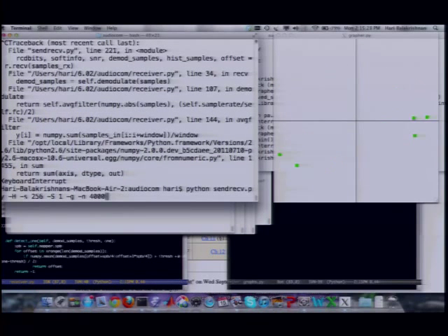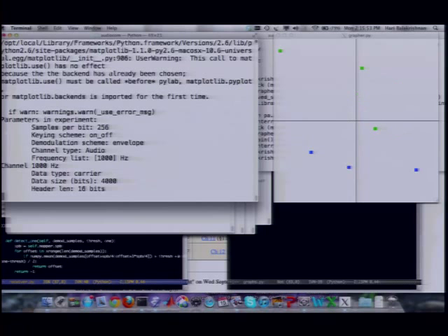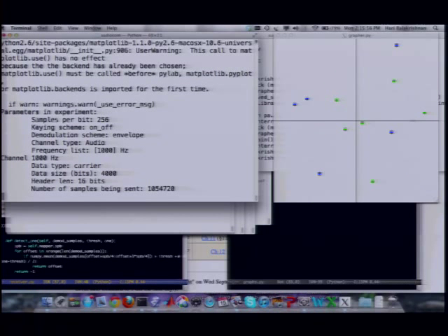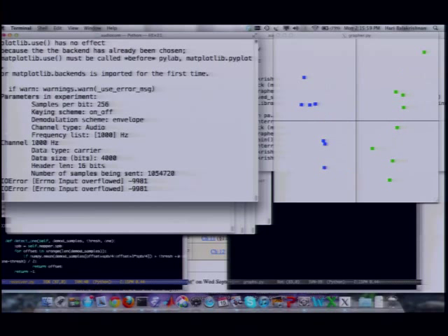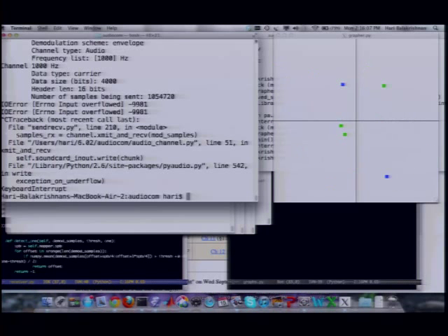As the amount of noise increases, you can imagine what's going on here in this signaling. This is called bipolar signaling, where you might send a bit 0 as a particular kind of sinusoid and a bit 1 as the other kind. So the idea would be that the zeros get mapped to the left, the ones get mapped to the right, and as we increase the amount of noise, you can start to see that they cross over, and we'll be making errors in our estimation. So things are working fine now, but as I make noise, or as you start talking and you create additional noise, we're going to start to see the effects of the noise. And this is annoying, so I'm going to turn it off.